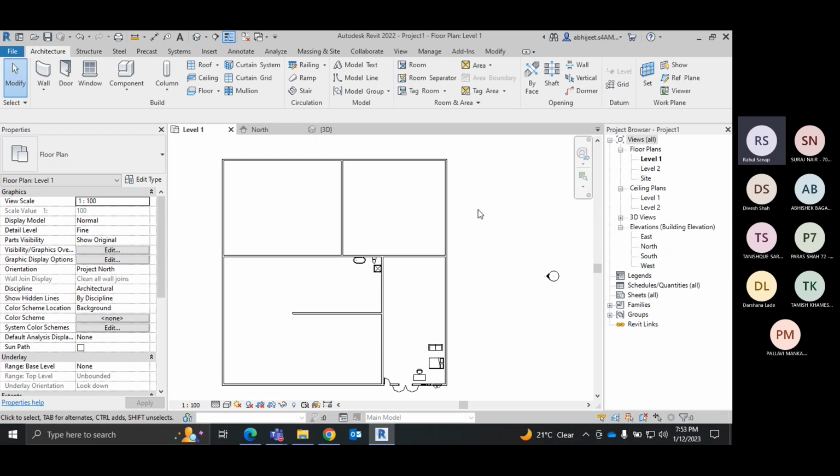The only major difference is whenever you are placing tiles separately, you need to place them with respect to the model in place element. Now what is the model in place? Model in place is a kind of generic model that we create in the 3D environment. Basically we are creating complex shapes according to your standard, so there is no standard or layer formula we are going to use over there. Whichever shapes you want to create, you just draft that shape and convert that object into a solid object.